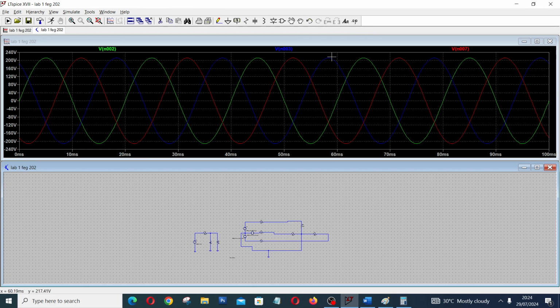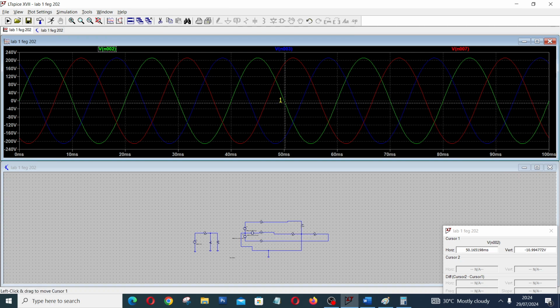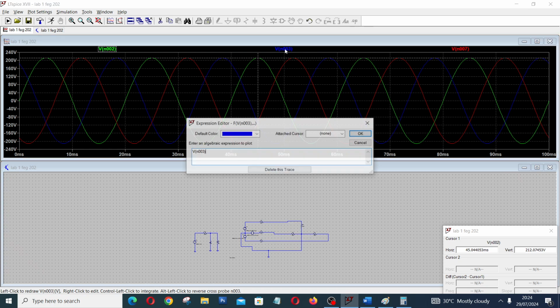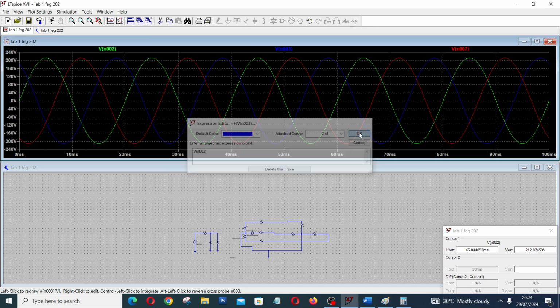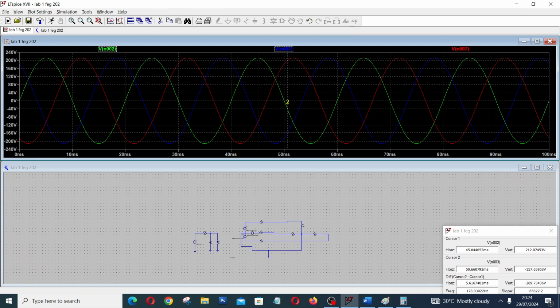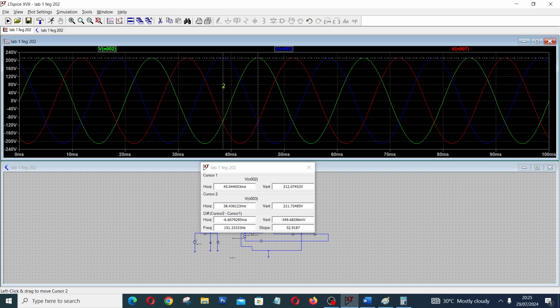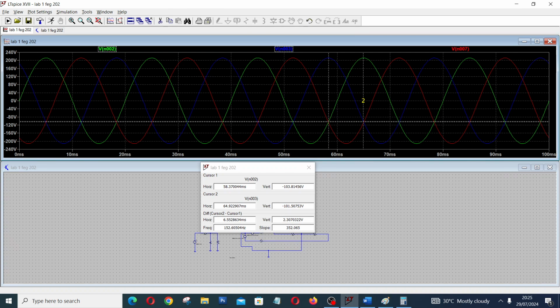and see how we do it. Just take any two sample waveforms, maybe V2 and V3. If I want to use V2 and V3, let's say I just click this V2. You know, V2 is color green. I use it to trace color green. Then I take V3. I make it cursor 2. This one is already bearing cursor 1. So that is blue. So you trace the peak. Let me bring the cursor values to our proximity. We are using blue and yellow. So let's look at the highest value we can get.